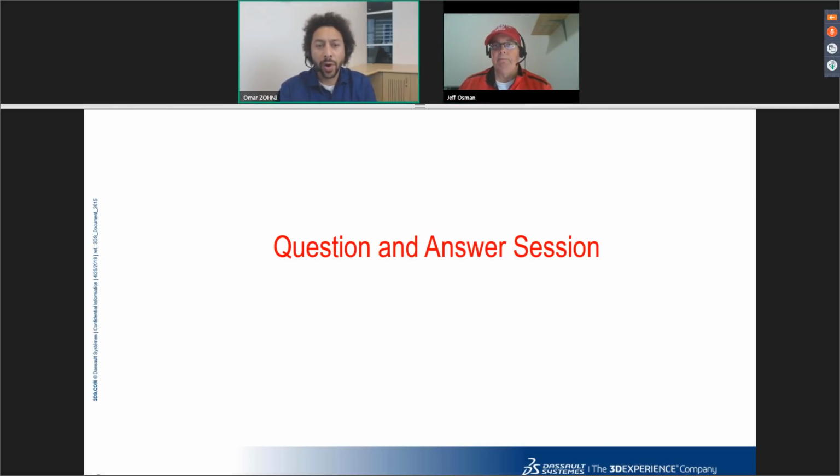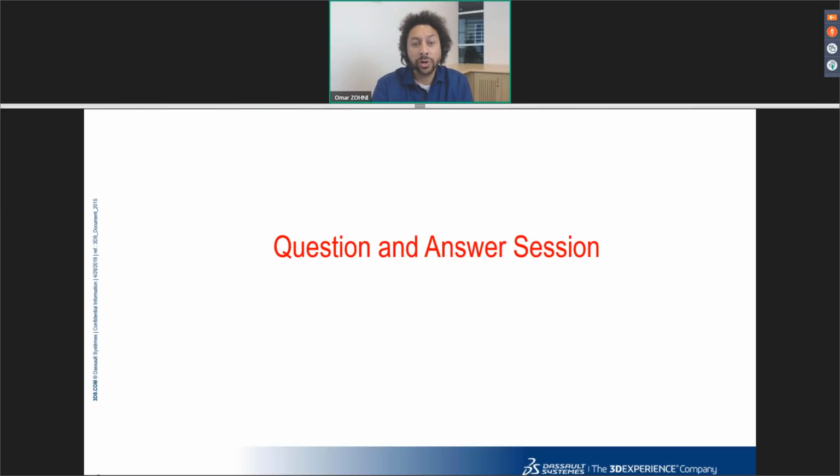Perfect. Question 4, this is for Andy Routsis. In general, should a rectangular part be gated from an end or from a side? Another good question. Yeah, in general, you want to gate a rectangular part from an end.